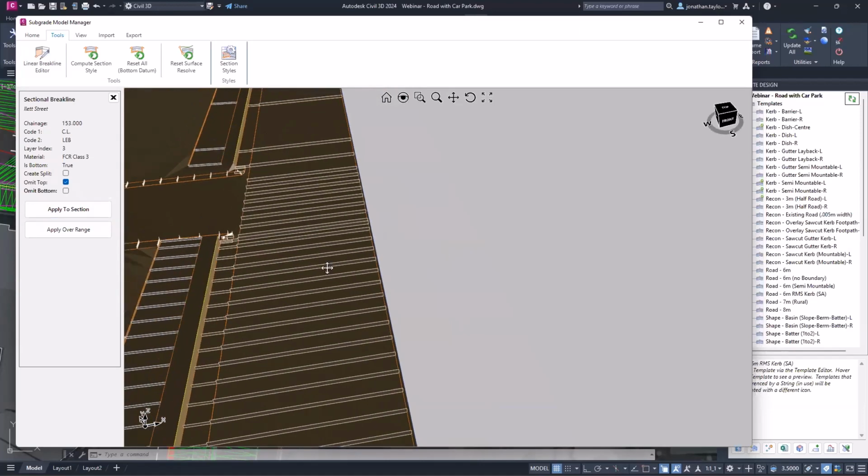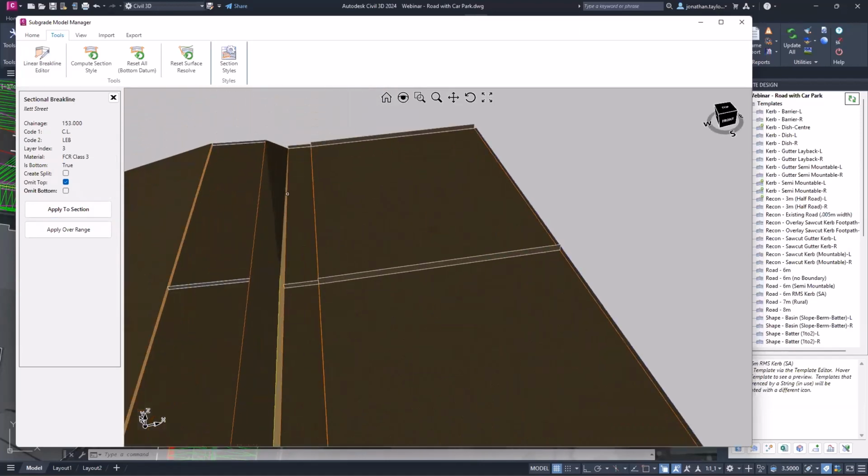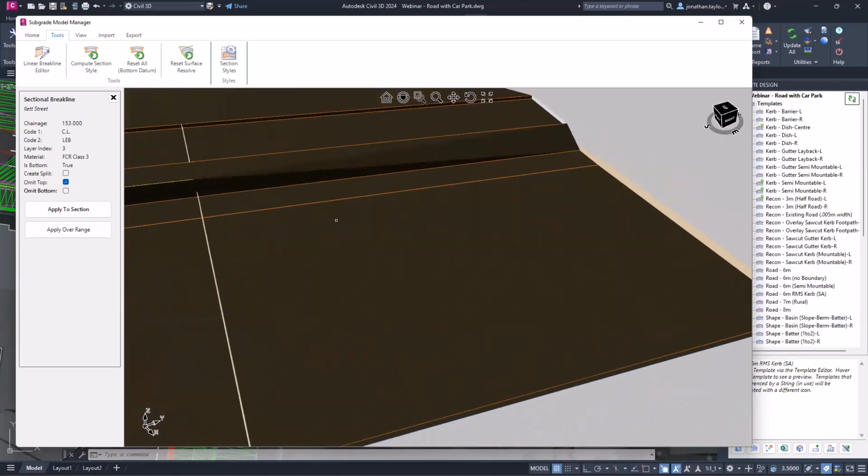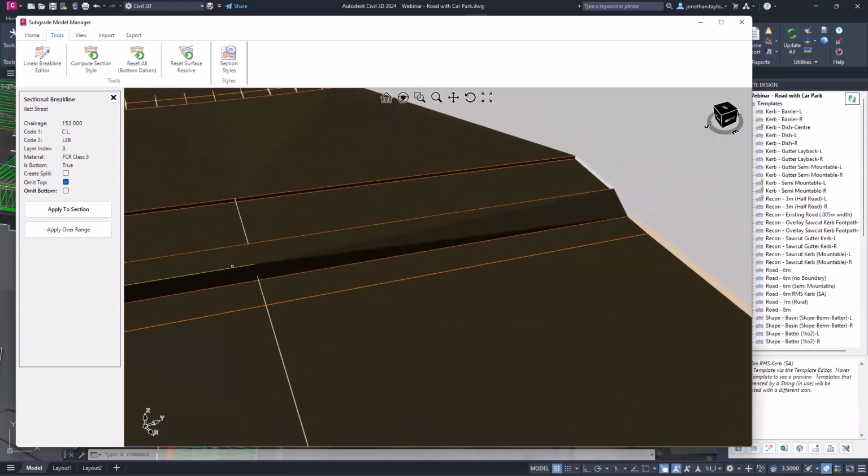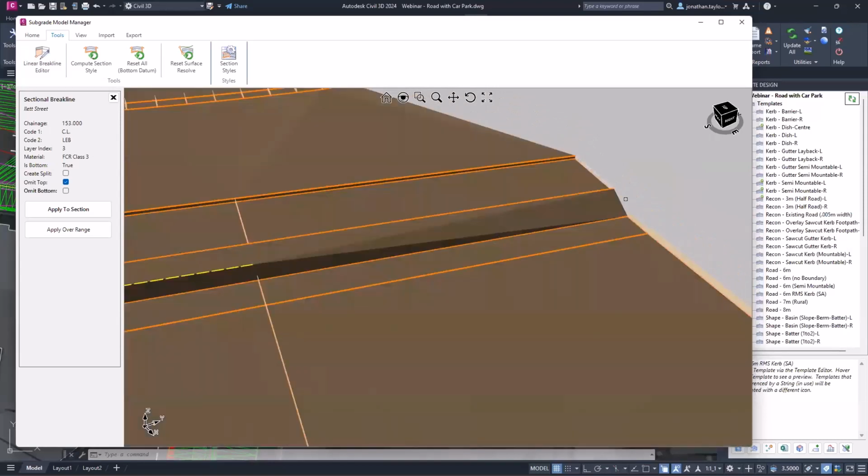Just a quick mention, because it happens on this job, and I wanted to show you guys what can happen. If it can't resolve, you will see that it won't resolve, and basically there's no resolve. For whatever reason, at this particular sample position, it can't resolve to the design, and that's due to the oblique nature of the alignment and the way it's doing the offset calculation.